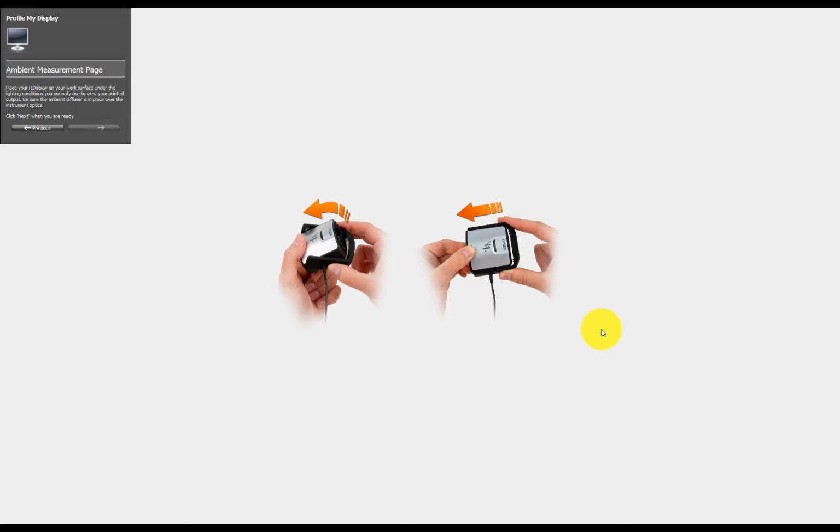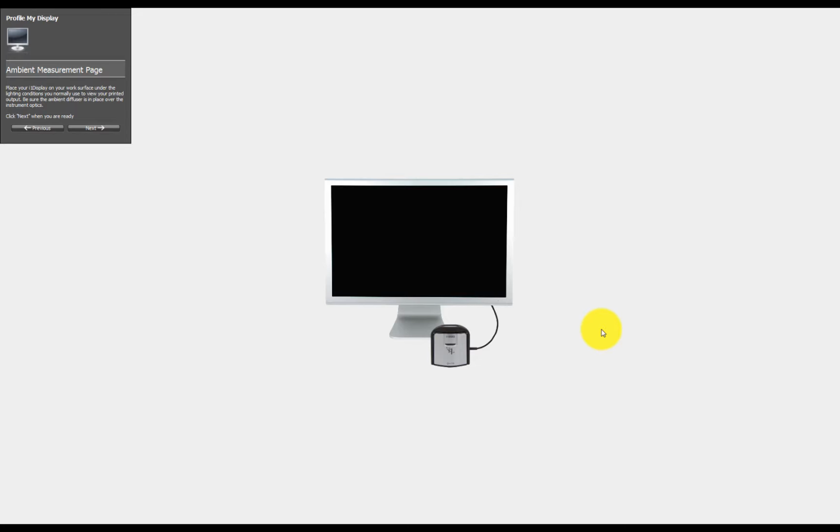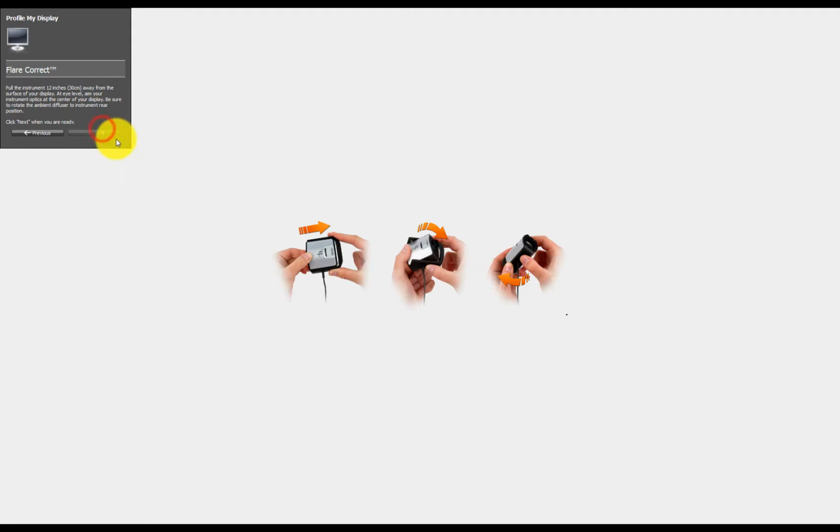We will be prompted to perform an ambient light measurement. Place the i1 Display on the work surface of our normal lighting condition for our work environment. Follow the on-screen graphics to make sure the ambient diffuser is covering the device's lens. Click the Next button. Our ambient lighting condition will be measured.